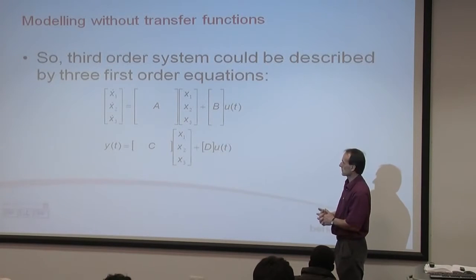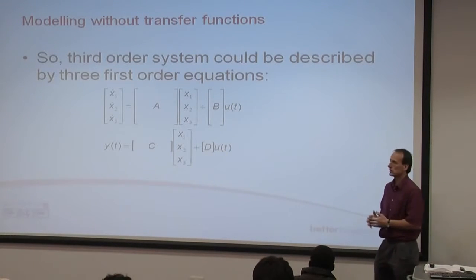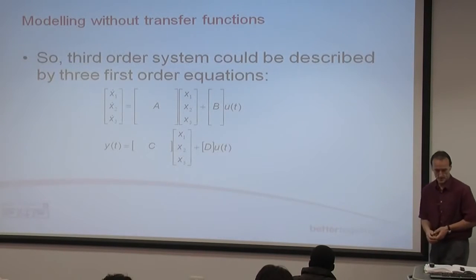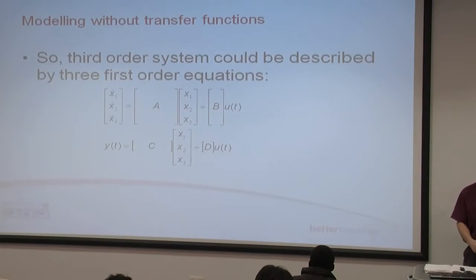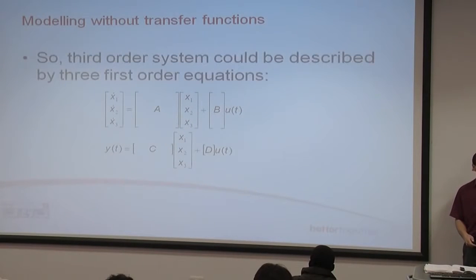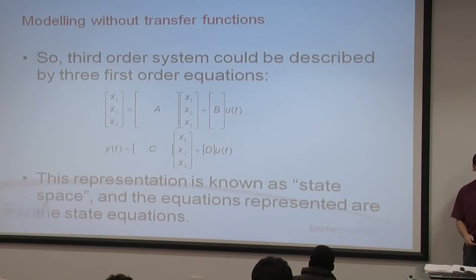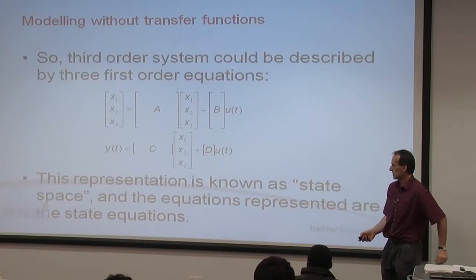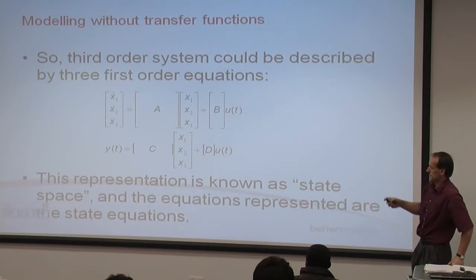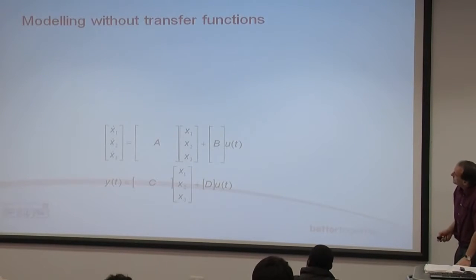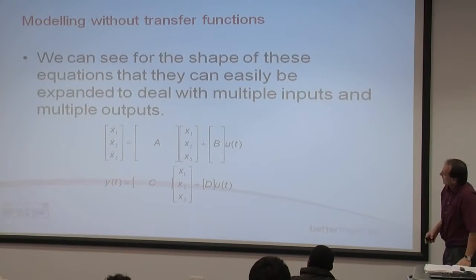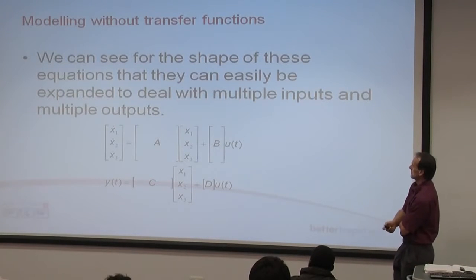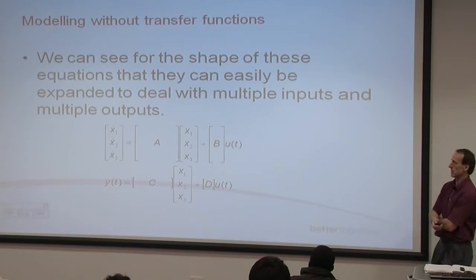But we can still have some very powerful control tools based around these state variables. That representation is known as state space, and the equations represented are the state equations. That's the top line. I've just said all this, really, can't I? We can extend these quite simply to deal with multiple inputs and multiple outputs.